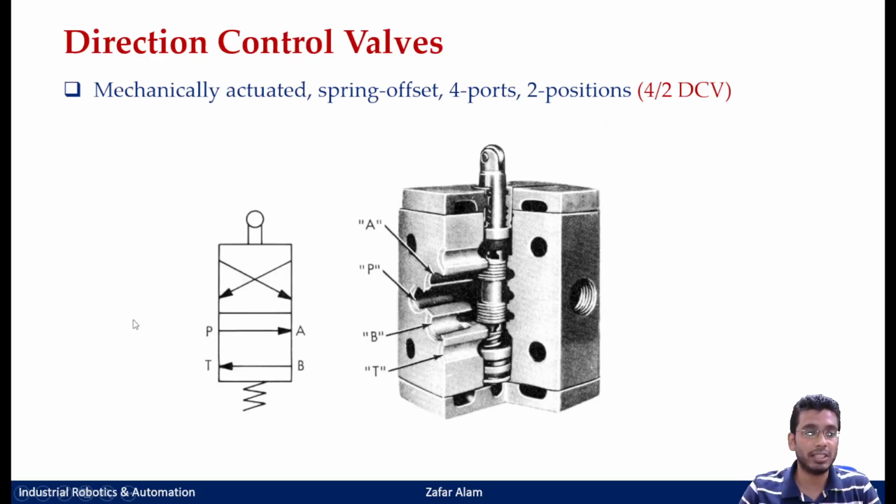Again, the mechanism is the same, you can have different configurations. For example, this is a 4/2. You can also have a 3/2 valve in this. You can also have a 5/2, right? But the actuating mechanism would be this roller valve here, or your cam mechanism, and your default position is the spring offset. Among these two positions, is the upper position your default or the lower position your default? Yeah, good. It is the lower position that is the default position.